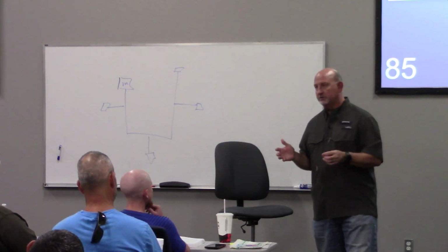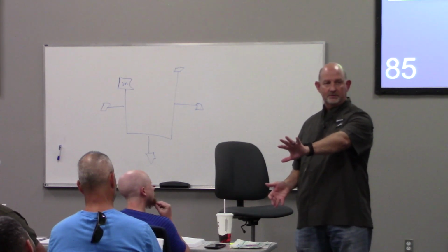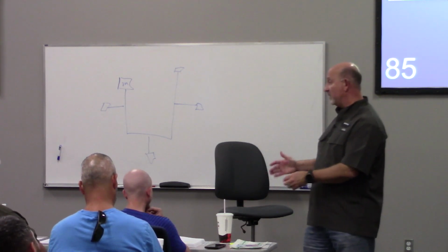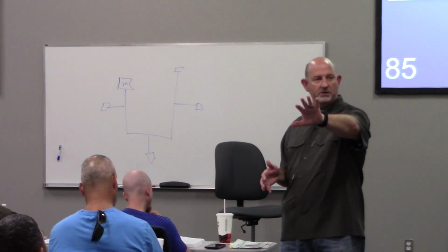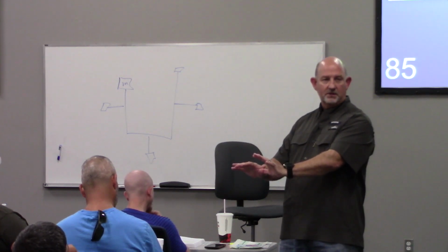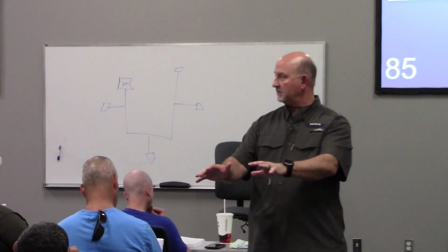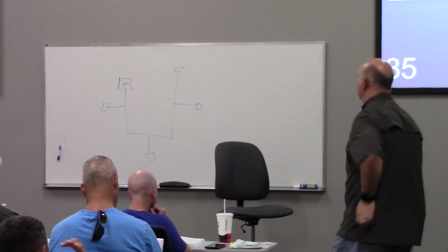Now remember, look at me again. If the room is big enough, we should have not read any of that. If the room is not big enough, we want to talk to him, but only if we're going to cut a hole on an inside wall. Do you agree if I want to cut a hole on an outside wall, I should not have read a word of this. I should have gone straight to 701.6. Make sense? You'll see why I'm making such a big deal about this in a minute. Let's move on to 701.6.